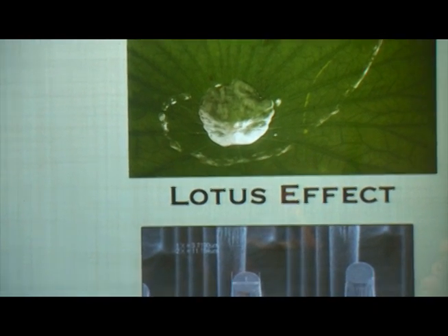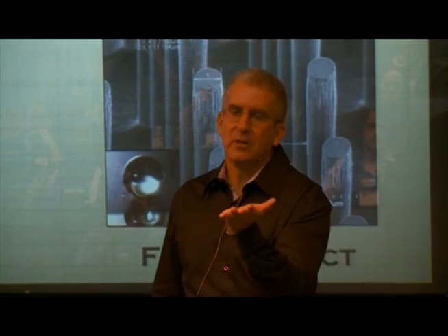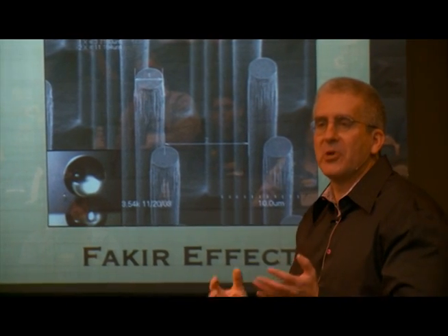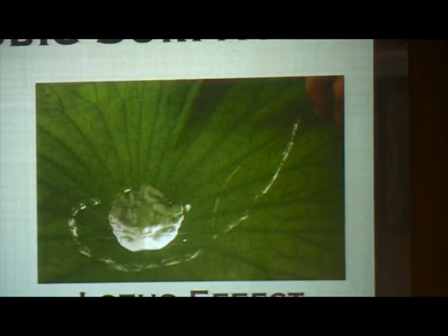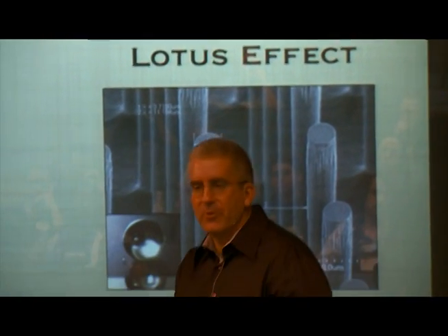The 2 basic mechanisms for doing this, the biological one is what's usually called the lotus effect. Lotus leaves, it turns out, shed water very easily. One of the things they feel is this is a biological adaptation to create a pool of fluid at the bottom of the leaf to nourish the leaf. When you look at the surface of the leaf under a microscope, you discover that there are many, many tiny hairs sitting on the surface. So when the fluid comes down to the surface, if it tries to push into the surface, it has to contact all those little fibers. And that increases the energy cost for that fluid-solid interface.